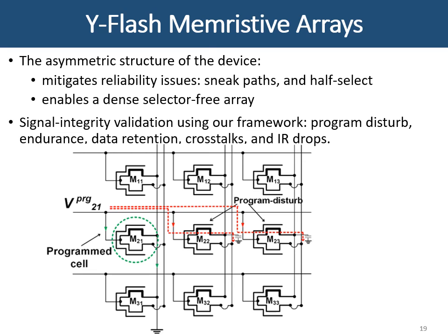The model allows the designer to incorporate the variation margin and hence qualitatively and quantitatively analyze its effect on the overall performance. Following RC extraction, crosstalk and IR drops can be evaluated and their implications on the design constraints checked.